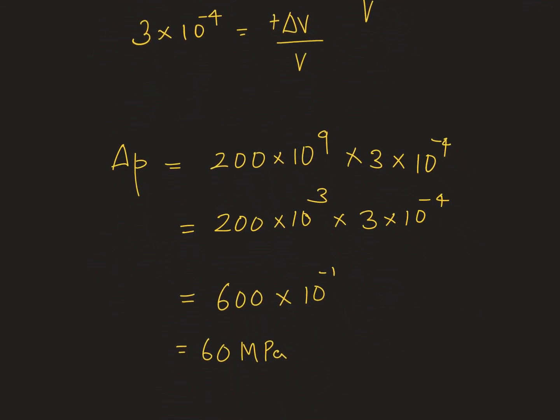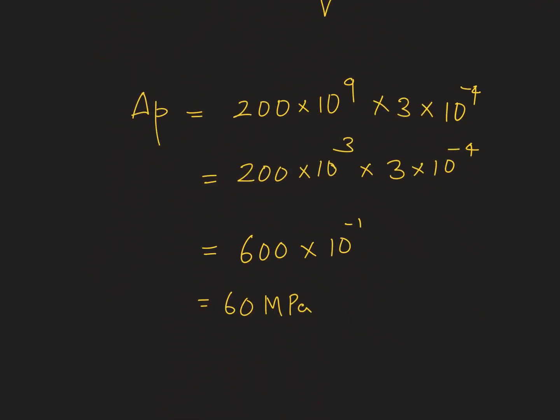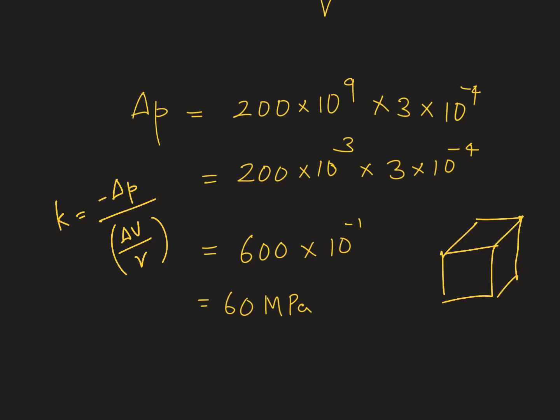Now, to compute the hydrostatic mean stress, it's fairly easy, because you remember the first expression we wrote: the bulk modulus is defined as minus delta P divided by the volumetric strain. I had this doubt, why this negative sign. It is because in a hydrostatic state of stress you have the stresses pointing inward. That's why the minus P comes into the equation. Make sense? You don't have to bother too much about it anyway.